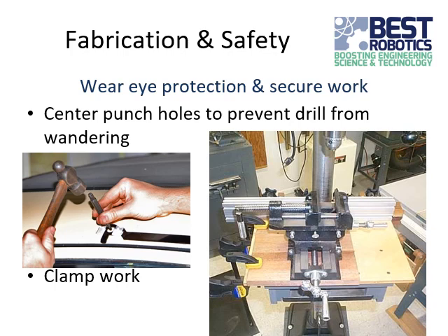If you're using the drill press, you need to make sure it's clamped down to the drill press table. A lot of times there'll be a vise or something attached to that already that you can use, but if not, you can clamp it down with normal clamps.